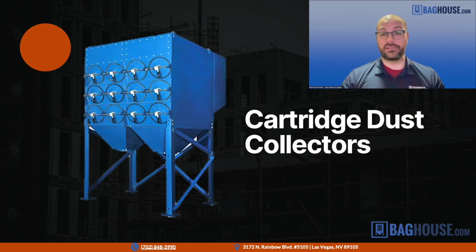Now, the downside of this is that because it's all jammed on there tightly, it's a little bit more difficult to clean the filters, and they can't quite handle the same dust loading or the amount of dust coming in as the baghouses. So we often use the analogy: the baghouse is like a big heavy pickup truck that you can do everything with. You can go off road, you can carry people, tow things, drive on the highway. Cartridge collector is more like a van. So if you're just carrying a lot of volume, light materials, big empty boxes, the cartridge collector, like a van, is a more practical system to have.